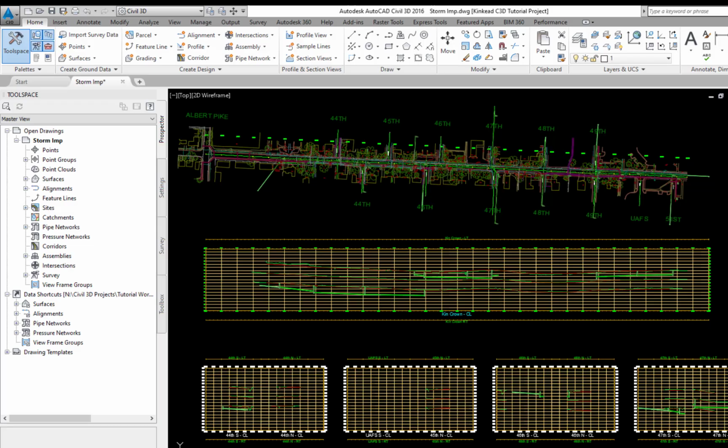The current drawing is a storm improvement-based drawing that was created using procedures set forth in video EX1A. The sewer improvement objects were incorporated into the project-based drawing using the procedures set forth in video reference sewer, and via XREF are shown in the current storm improvement drawing. All Civil 3D drainage objects should be created on the storm improvement drawing.